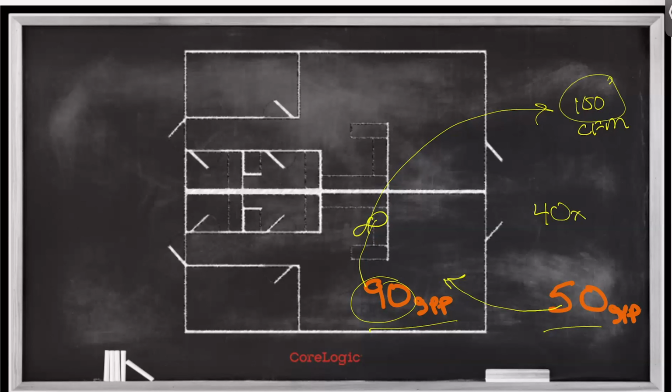So now I'm going to get a grain depression between these two of 40, times a CFM of 100, and divide that by 71. Just by turning on the kitchen exhaust fan, I can do 40 times 100 divided by 71 and get 56 pints of dehumidification. That's like adding another small dehumidifier, right? Now do the same thing in the bathroom for another 100 CFM. That's another 56 pints of dehumidification, right?